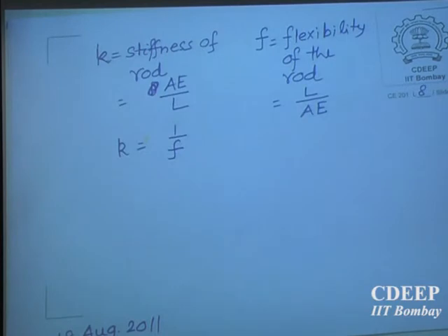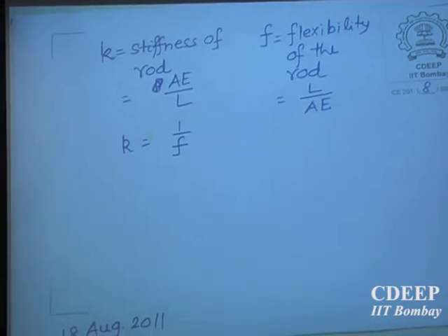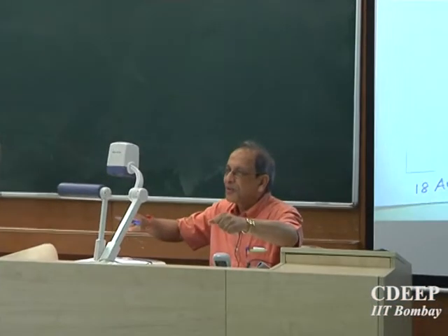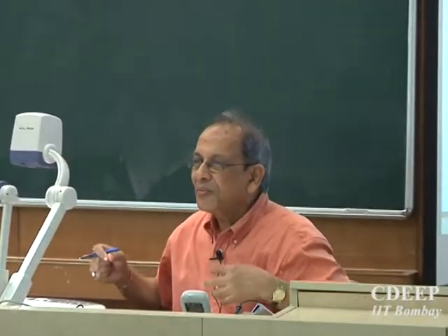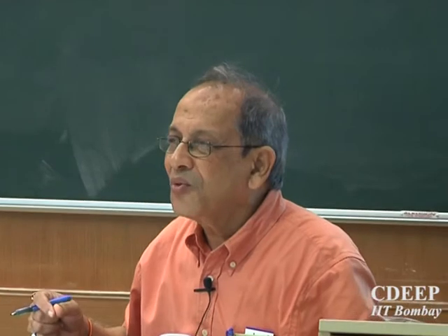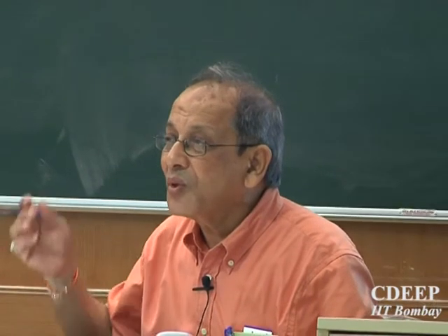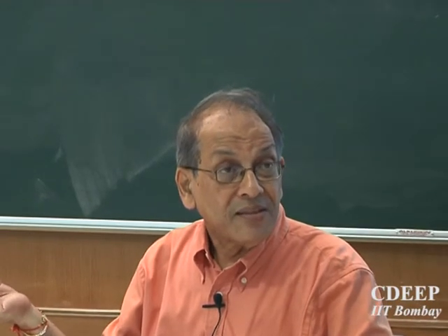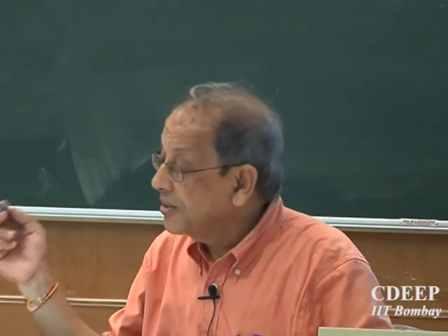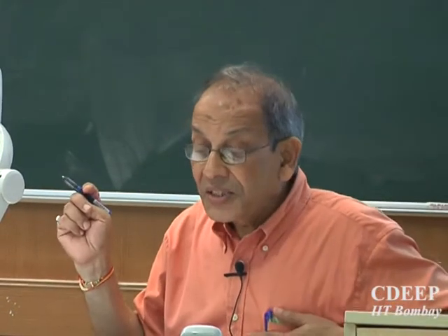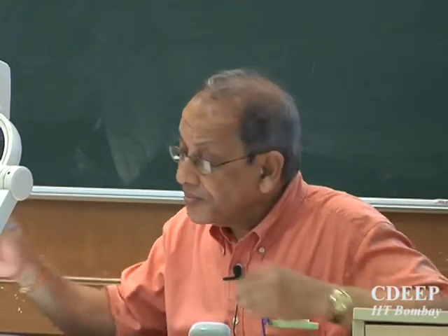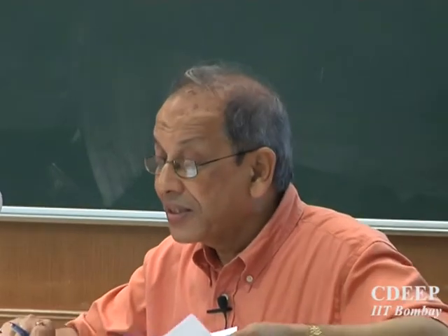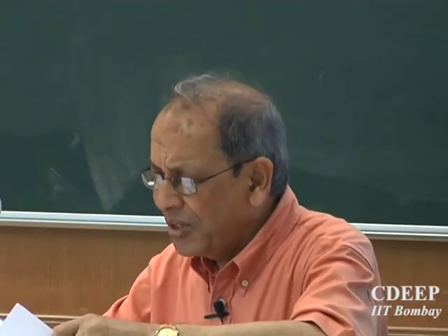Force required: how stiff is this rod? I will ask what is the force required to give me unit displacement. If there are 10 rods, you find out the forces required. The rod which takes the maximum force will be the most stiff, and the inverse will be the flexibility. So this is what you should remember, because we will be using these concepts later.